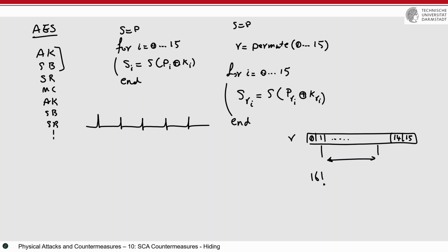And then sometimes here an S-box for state 1 is processed, and a state 3, and then a state 2, and then a state 10, S15, and so on. The next trace that you measure is very well fully aligned, but it will be S2, for example, S10, S3, S15, S11, and so on. Then when you perform the attack, at this point in time, everything is well aligned.